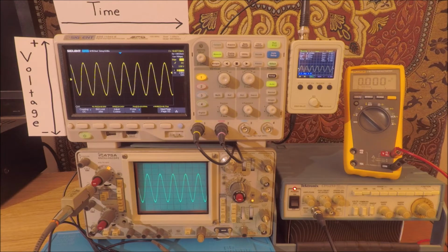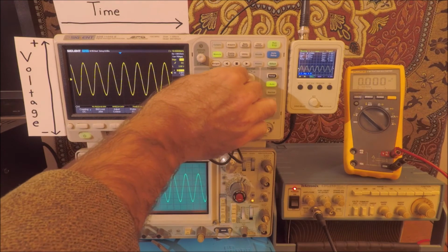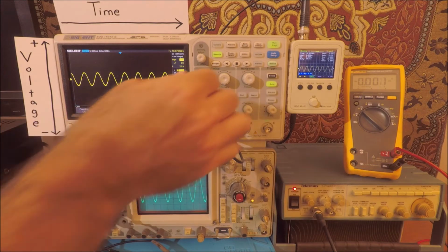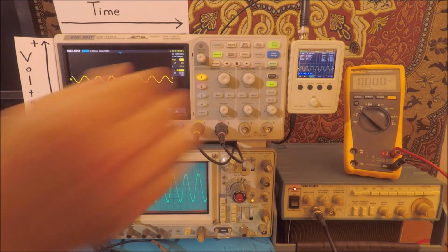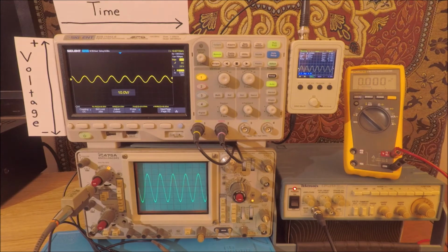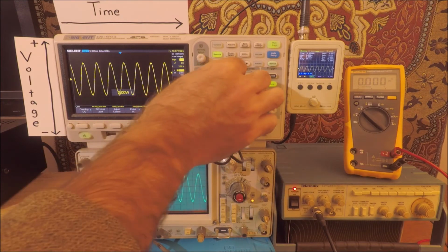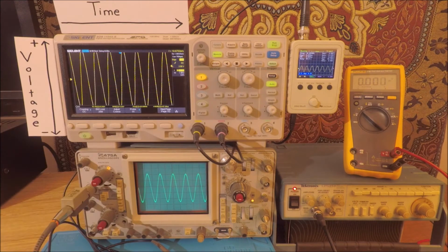The digital oscilloscope in the top here has the same control. It's just labeled differently. They just call it the vertical control right here. Now, this being a digital scope, this is a digital encoder, but it's going to function in the same way. So currently, we're also set at 2 volts per division. We can change this, and now we're reading 5 volts per division, so we're zooming out on the vertical, and zooming out further at 10 volts per division. And we can go the other way as well. Put it back to 2 volts per division and zoom in at 1 volt per division.